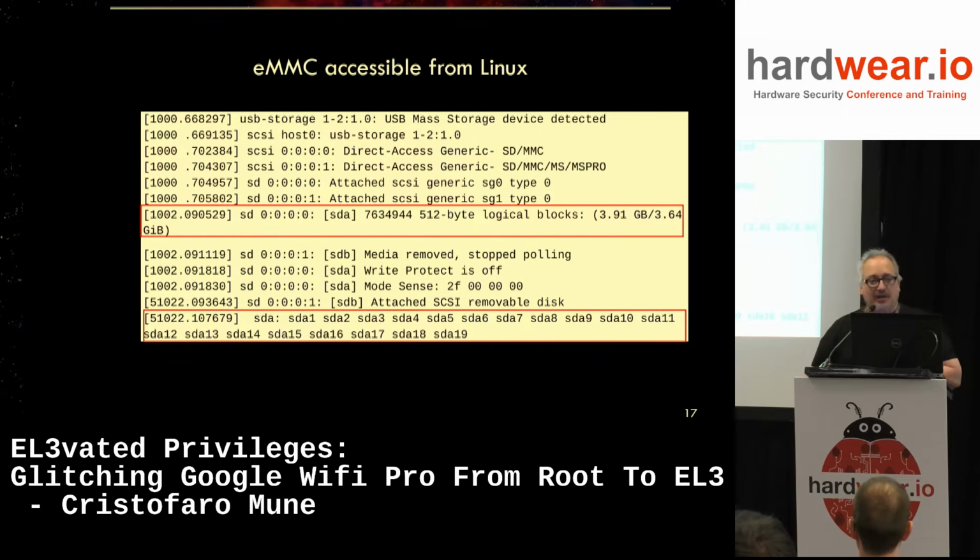I don't want to do a chip-off and put it back every time we read and write. It's also pretty annoying to solder BGA. It's doable, but annoying. So if you can just do it with a wire, in the end it was just a matter of finding this clock signal and removing the capacitor.